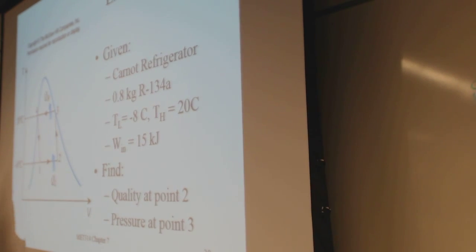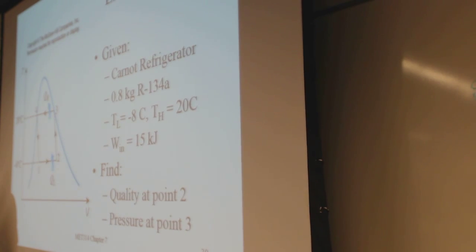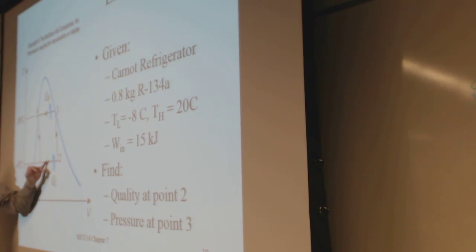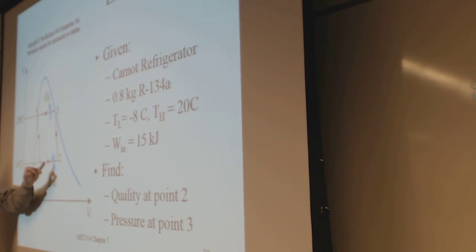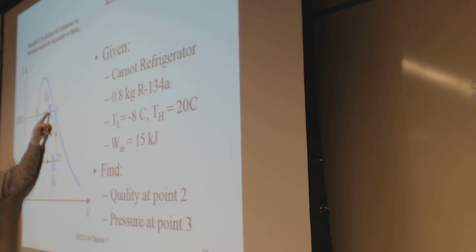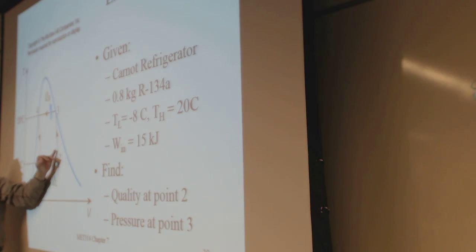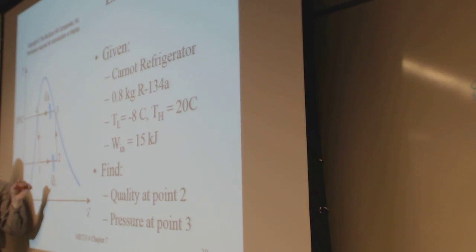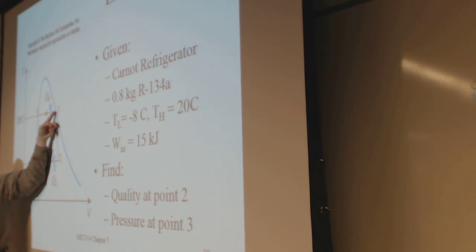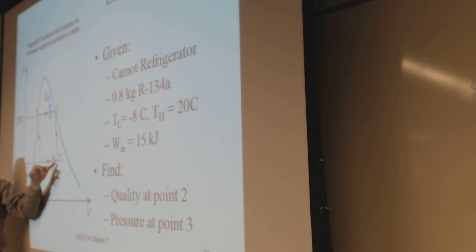And they're doing this inside of the saturation dome. One reason for doing that is it does give us Carnot efficiency, said the heat flow all has to happen at a constant temperature. And so when you're in saturation, you're changing phase, and by golly, that meets that criteria for Carnot of a constant temperature low heat, a constant temperature high heat. In this case, you bring it up, and you can do a constant entropy process here, adiabatic and reversible, slow enough reversible, whatever.